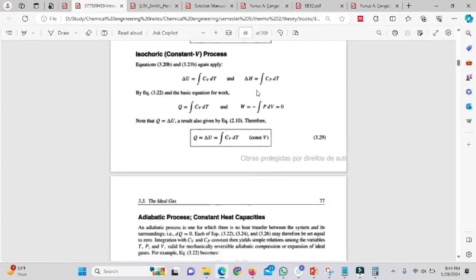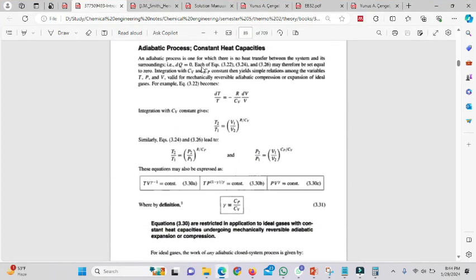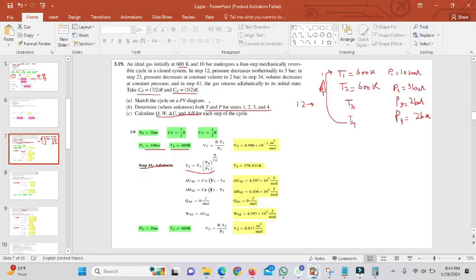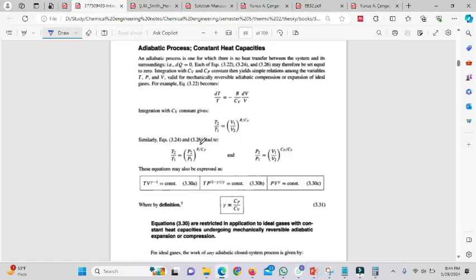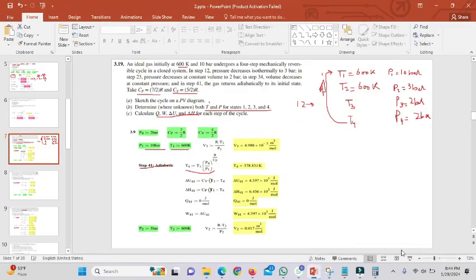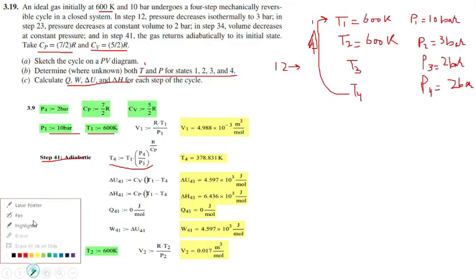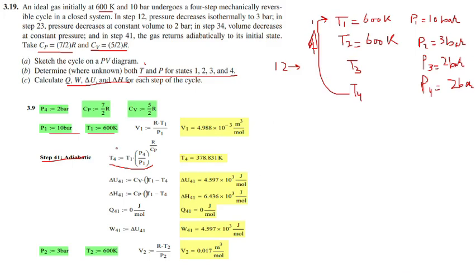So this is a book, and these are the formulas for the adiabatic process. So I am using this formula. Okay, so T2 here means final temperature, T1 means initial temperature. So in our case the final temperature is state number 1, and the initial temperature is state 4. This is initial, because you are going from 4 to 1, so you will write your formula accordingly.